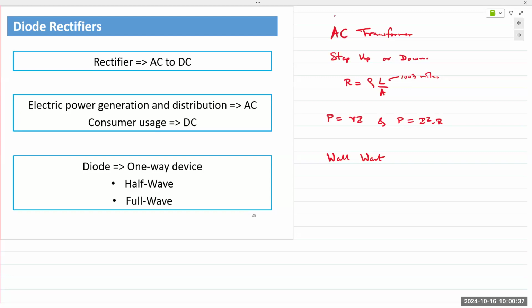That is still what you have with your laptop adapters and your chargers, except now with better design and better functioning transformers, the AC is directly converted to DC at hundreds of volts, and then it's converted back. It's stepped down, DC to DC conversion, and then it's converted back into AC. So now the transformer size is very small, and that's why it's lightweight. So the circuit is exactly the same as an original wall wart, except now it's directly rectified at high voltages.